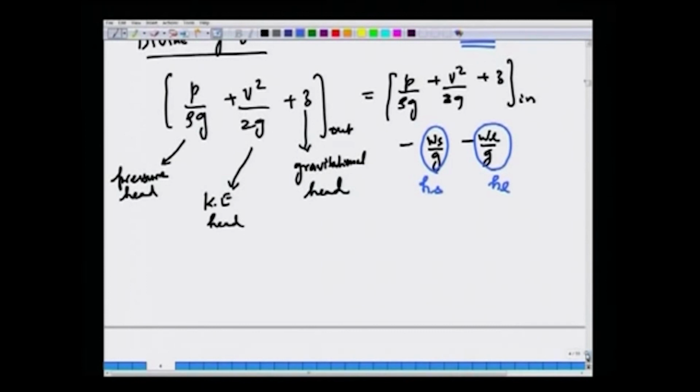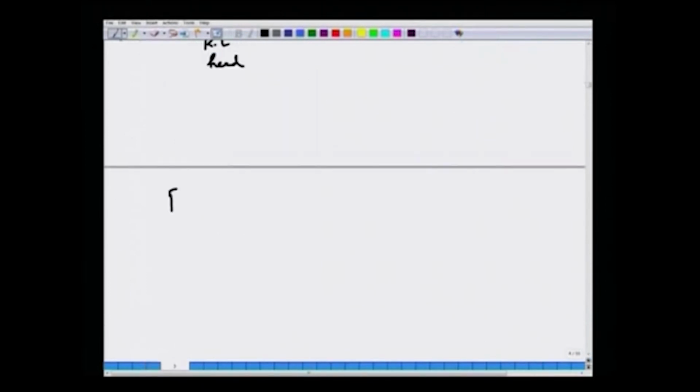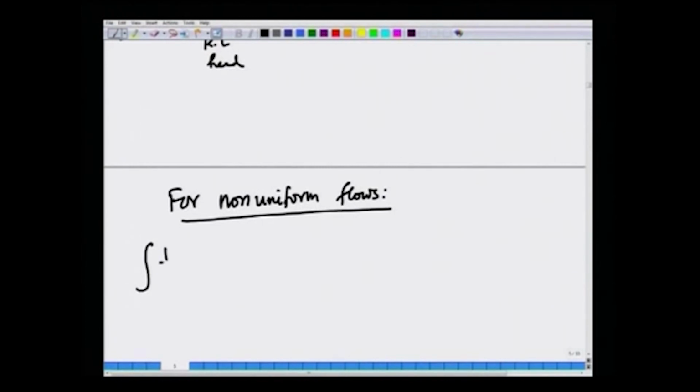Okay. Now, that is the simplest form of energy balance. As we told in the last lecture, for non-uniform flows, where the velocities are a function of the cross sectional area, then just as we introduced the momentum correction factor in the last lecture, for the flux terms in the energy balance you may have to carry out this integral. If you recall, you have a term of the type rho half v squared v dot n dA over the control surface.